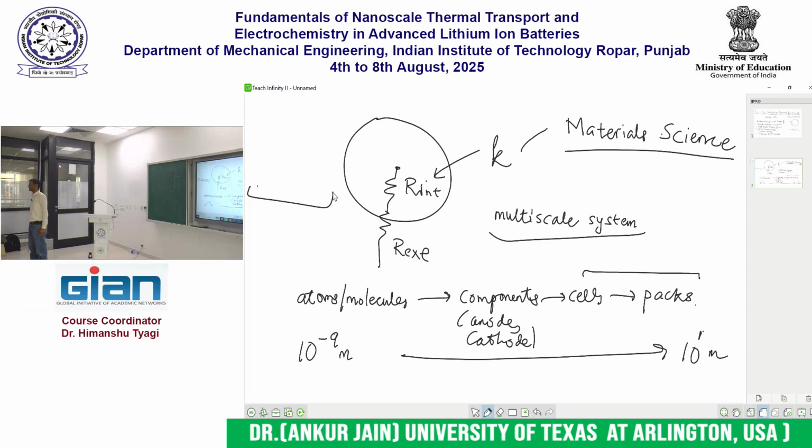Particularly in the case of cargo planes, one interesting challenge is that the temperature up there is very different from the temperature on the ground. Typically it's very cold up there at the heights that the plane travels at, and the pressure is also very low. The cargo hold is not pressurized. So the batteries are seeing very low pressure ambient. And that's a problem because inside the battery there is very high pressure.